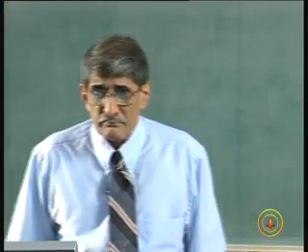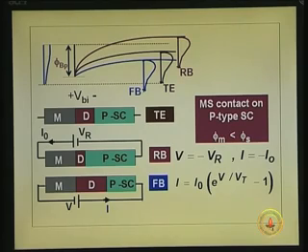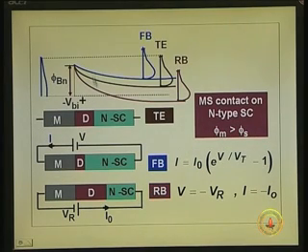This is a diagram which is redrawn, showing only the conduction band. For example, here you have got 3 curves which are the conduction band represented for thermal equilibrium, T referring to thermal equilibrium, RB referring to reverse bias, and FB referring to forward bias. On the left hand side, which represents the metal, I have also given the density or distribution of electrons above the Fermi level.